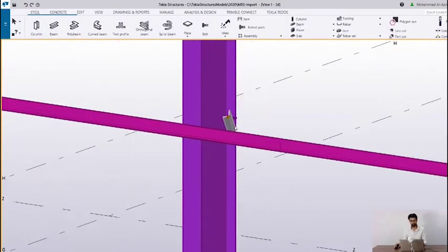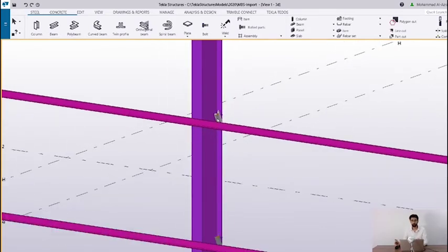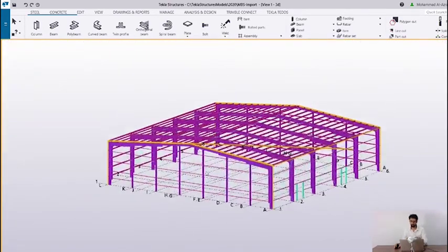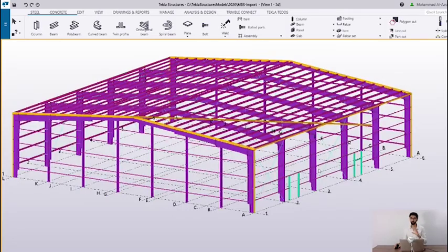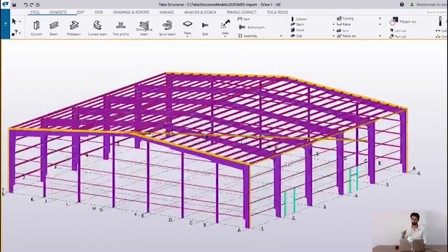If you see any clashes, that means there's something in MBS you didn't fix, because in MBS it gives you warnings. You need to fix these warnings, then you'll get it fixed in Tekla Structures. Besides this, after you finish importing the data in Tekla, when it comes to the drawing aspect, we have some tools that can make drawing generation easier. You can make erection drawings and frame drawings with the help of these tools. If you want to try them, please get in touch.